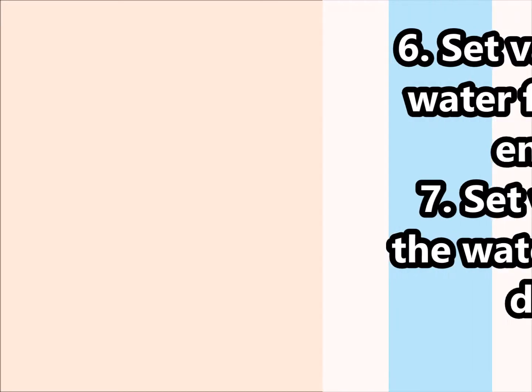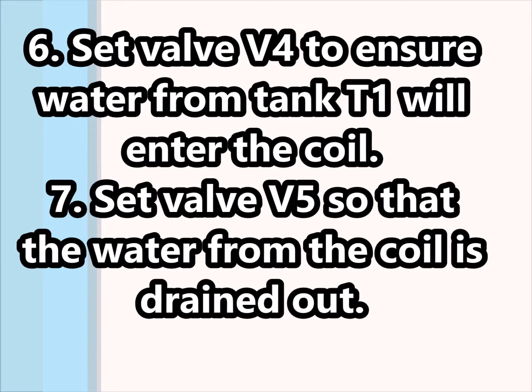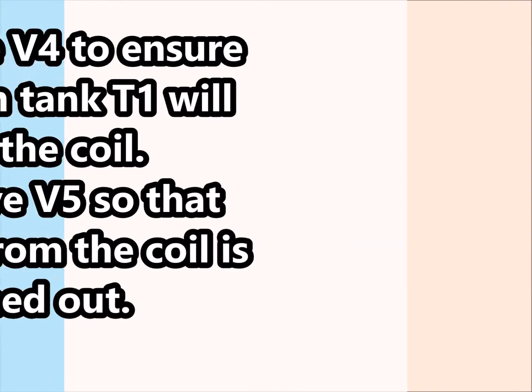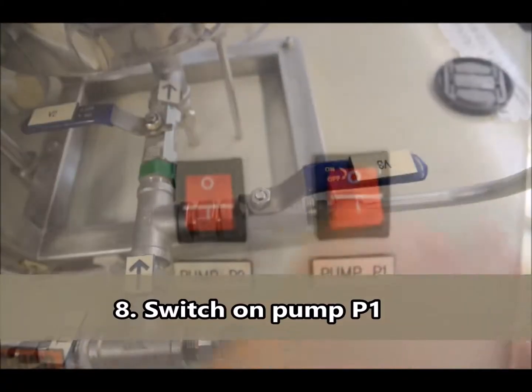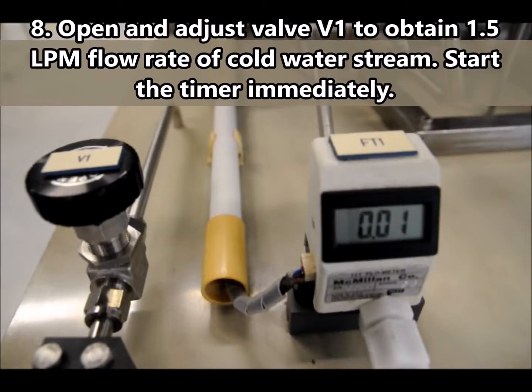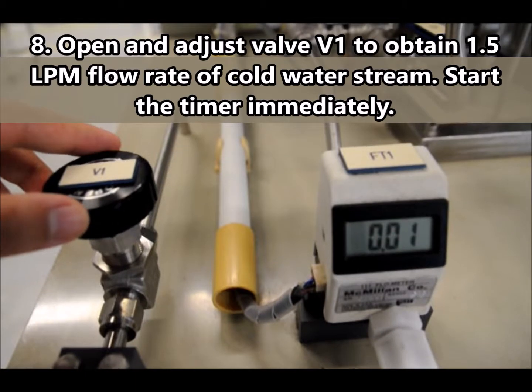In step 6, set valve V4 to ensure water from tank T1 will enter the coil. 7. Set valve V5 so that the water from the coil is drained out. Open valve V3. Switch on pump P1. Open and adjust valve V1 to obtain 1.5 liter per minute of flow rate of cold water stream. Start the timer immediately.